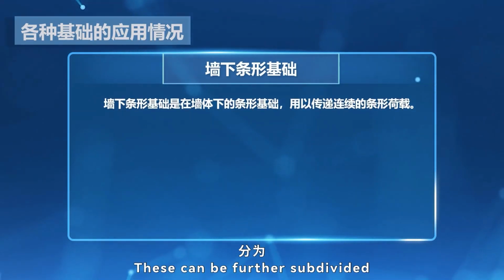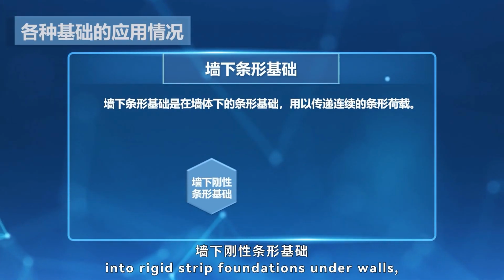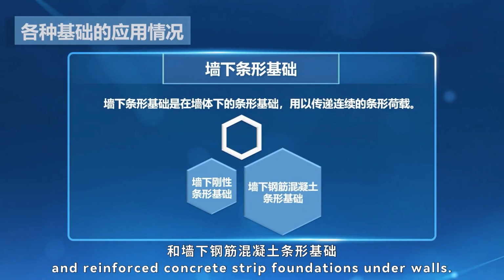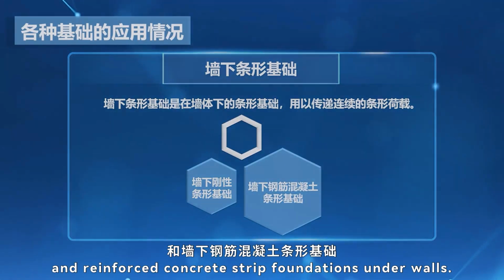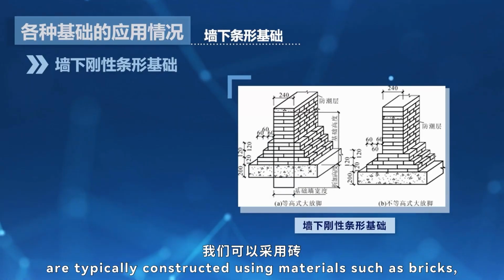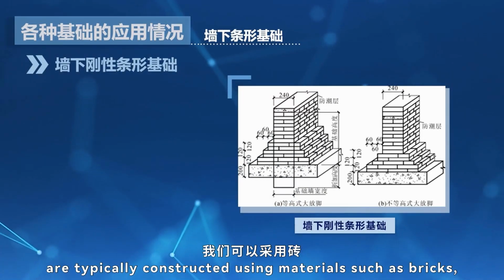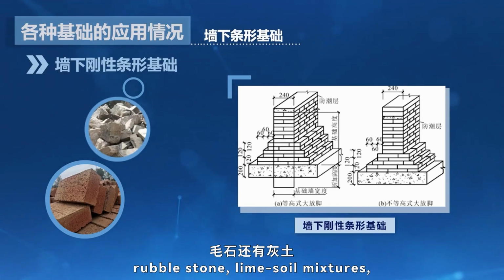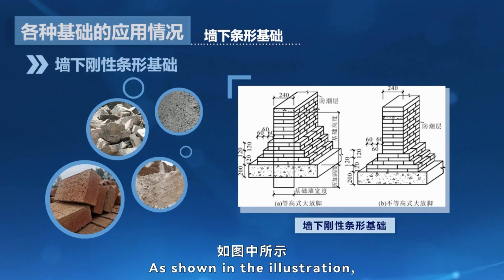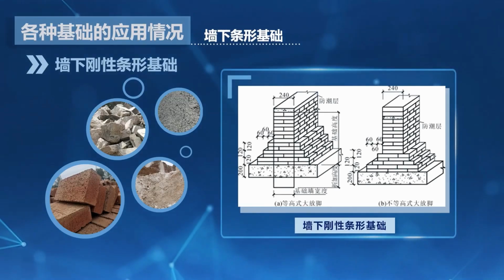These can be further subdivided into rigid strip foundations under walls and reinforced concrete strip foundations under walls. Rigid strip foundations under walls are typically constructed using materials such as bricks, rubble stone, lime soil mixtures, or plain concrete, as shown in the illustration.